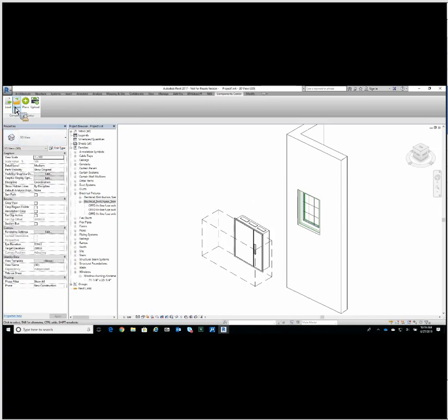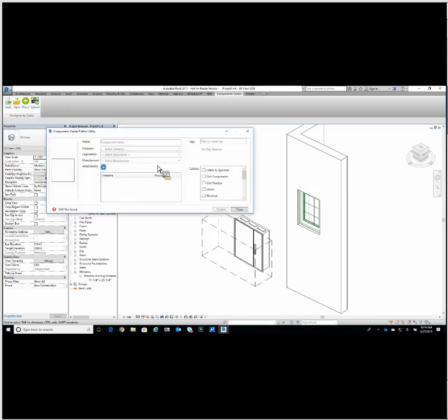You'll notice that you can also open something up. So in this case, if I wanted to, I could start a brand new RFA session. I could open an RFA from Component Center, modify that, and then use the upload feature to take that RFA and publish it back up to Component Center as a new proposed component.